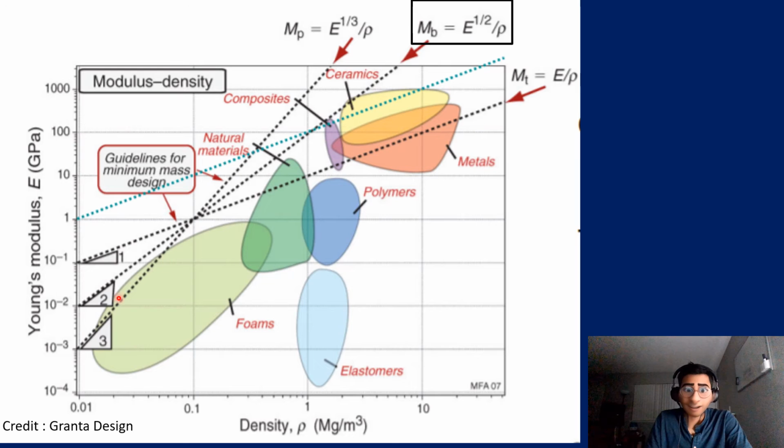These are the slopes. We previously looked into Young's modulus chart, but in Ashby's plot, it's software and you can pretty much define the slopes. And in our case right now, our objective function is slightly different than what it was previously. Now, for this material index defined for this bending case, our objective is to maximize this particular function.